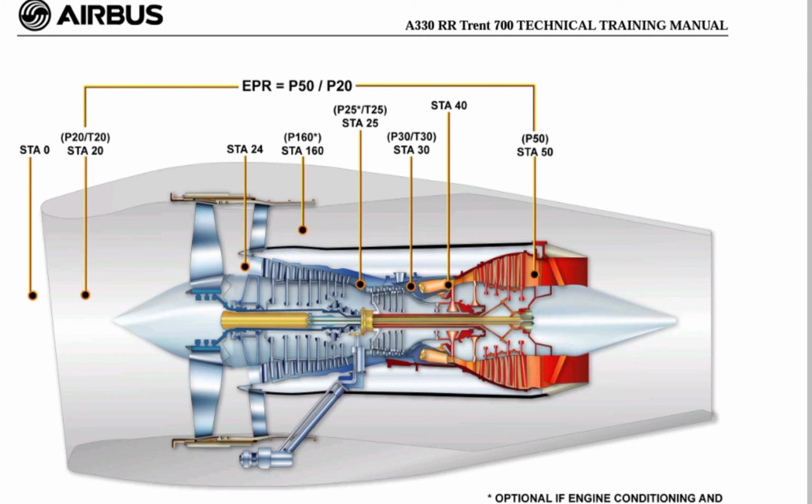The exhaust gas temperature, EGT, is measured at the inlet to the LP turbine, which corresponds to station 49.5. 11 thermocouples are installed approximately equally around the engine within the LP turbine nozzle guide vanes and transmit the EGT signal to the EEC.